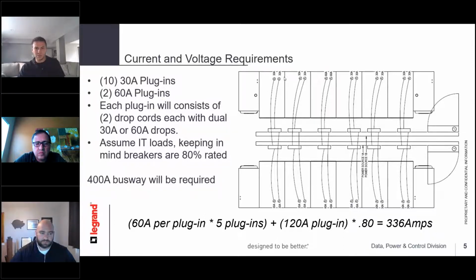So as specifying engineers, while you're going through these and looking at this that says 30 amps here, we would expect a note somewhere saying, hey, this is a 5-wire, and if the NEMA configuration or the IEC 60309 configuration is known, it's good to call that out. It helps the PDU guys know what they're putting in there. It helps us on the busway side, the sales reps, and the end user to know what kind of cable they're ordering in that area. The same goes with the 60 amp too. There could be lots of different options, especially at the 30 amp level. These could be pin and sleeves, they could be NEMA configurations. There are lots of different ones out there. So specifying those is important as well.